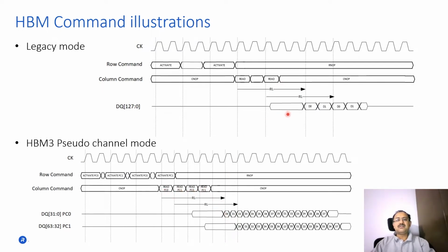While one could think that in the earlier case the data was 128 bits and it was fetched together, here with just one CK cycle delay, we can have fetching of data from 2 different rows. This is particularly suitable for AI applications where you are looking for 2 different data from 2 different pages, which are spaced apart in different rows.